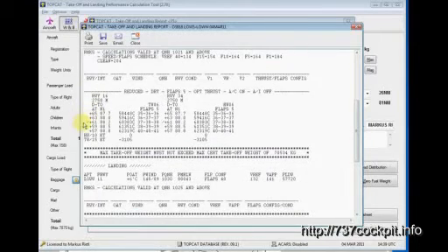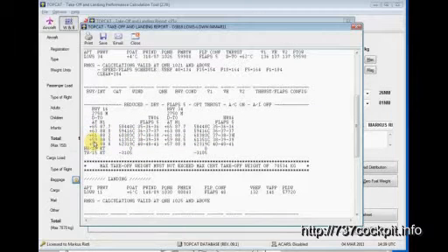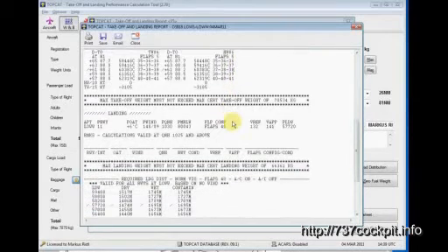Our takeoff calculation is marked with a slash before. Slash means that this is the calculated outside air temperature, so that our engines will give a thrust of 88.2%, which leads us to 137, 138, and again 138 V speeds in flaps 5 configuration.